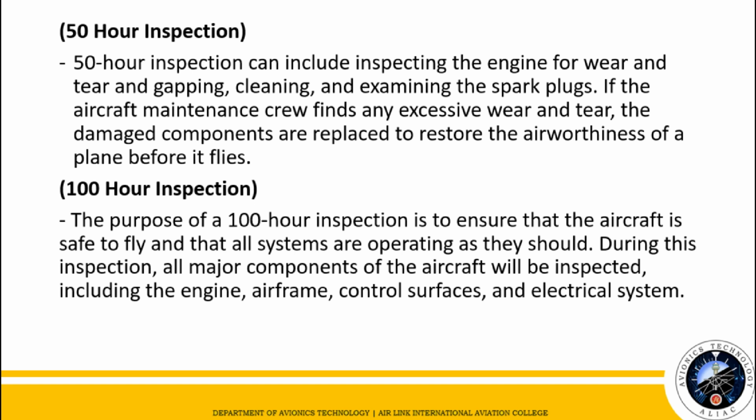It is typically performed after 50 hours of flight time or every 3 months. So, overall, the 50-hour inspection is a critical aspect of aircraft maintenance and helps ensure that the aircraft is safe, reliable, and operating at peak performance.